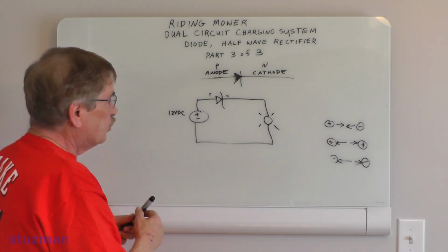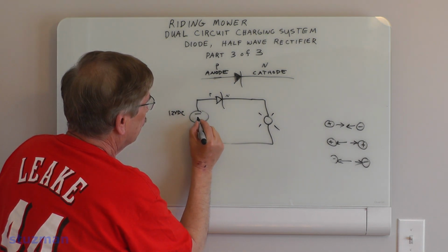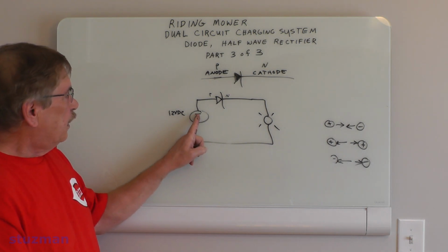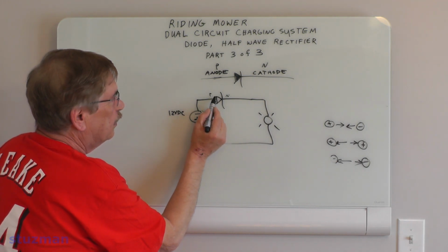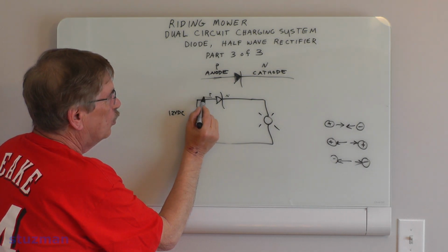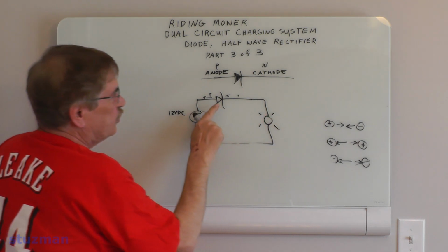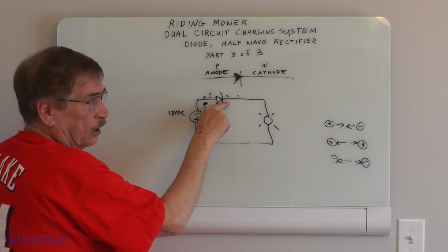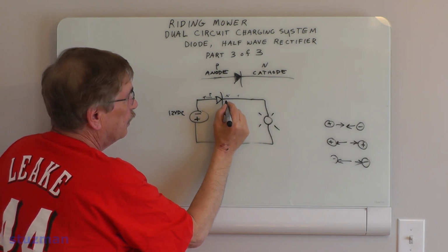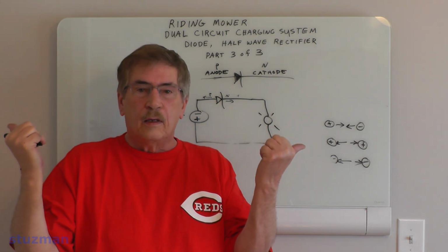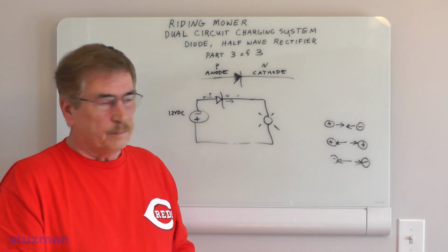All right? And if I was to reverse these connections, can you see now that the negative here and the positive attract? So now it's going to be taking the positive charges out of the P-type, pulling them this way. And then over here we have the positive coming up. And you can see that the negative charges in the N-type material are getting attracted to the positive from the battery, getting pulled away. So now they're pulling apart. They're not going to be crossing that P-N junction, so at that point, the diode is going to be open.